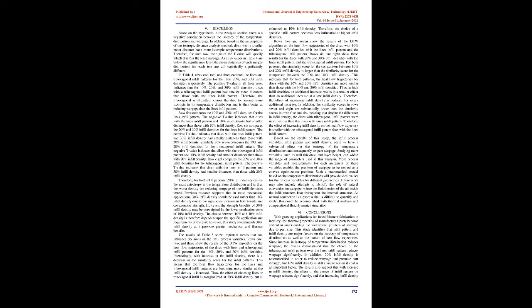The positive t-value indicates that disks with the trihexagonal infill pattern and 30% infill density had smaller distances than those with 20% infill density. Therefore, for both infill patterns, 20% infill density causes the most anisotropy in the temperature distribution and is thus the worst density for reducing warpage of the infill densities tested.